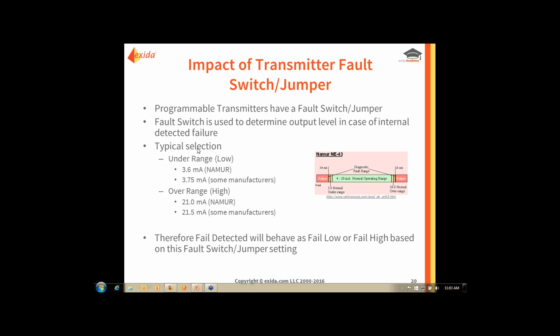One more here. Does HART diagnostics impact the overall calculation? The answer is no, because no HART signal can be communicated to a safety critical function. HART is not considered safety critical. HART is considered interference free. Whenever an analysis is done on a transmitter or even on a logic solver, the HART circuitry is typically looked at to make sure it doesn't impact the analog capability of the transmitter. Obviously, yes, you can get information out of it, but we don't take any credit for it in the calculations.